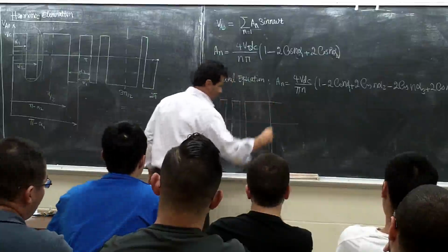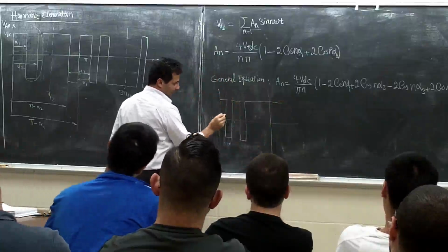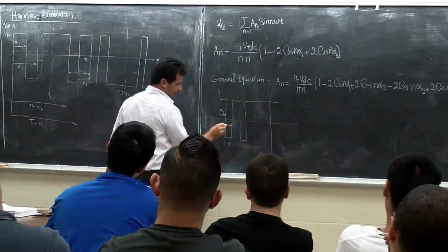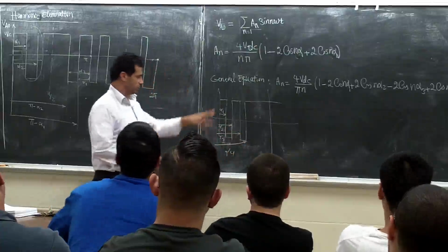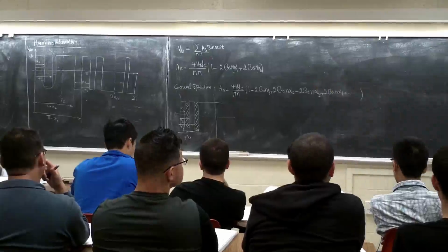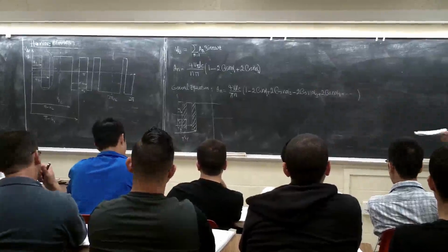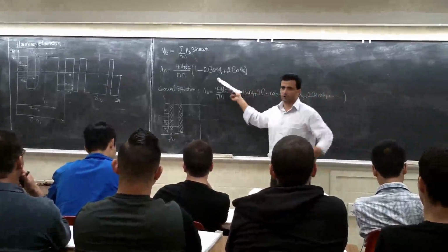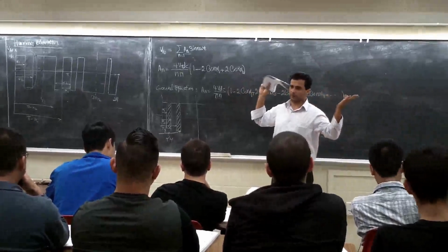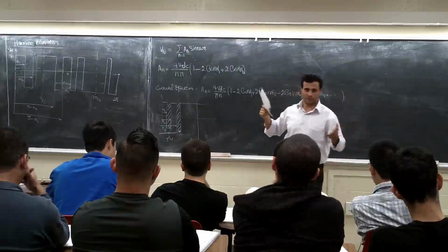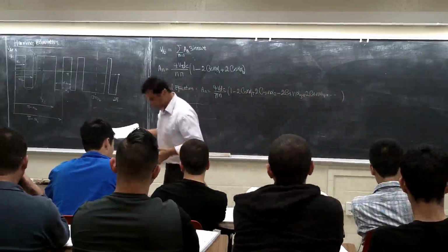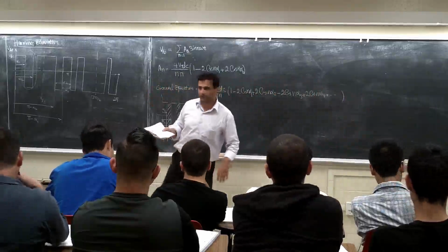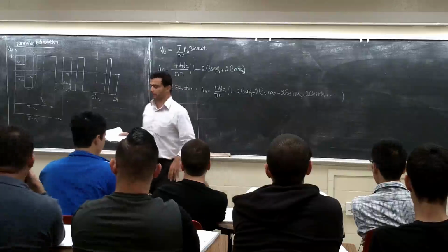Let's say this is a quarter cycle, and after that it is going to happen. Here I have alpha 1, alpha 2 here, alpha 3 here, and alpha 4 here, right? These are two notches. You have an alpha 1 and alpha 2, so you can only select these two such that harmonic 3 will be 0, or 5 will be 0, or the fundamental will be this much. But if you have 10 notches, you can go up to harmonic 11, 15, something like that, to cancel them.